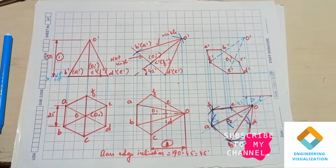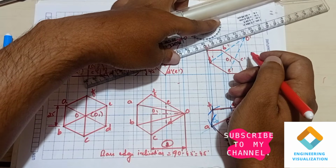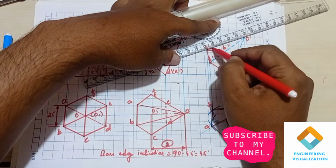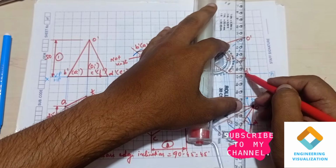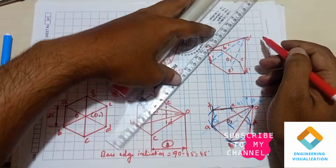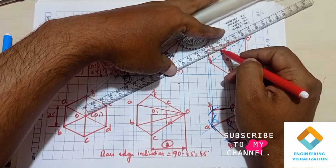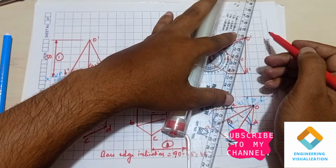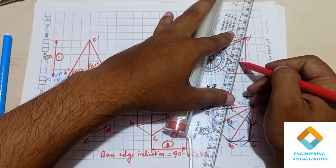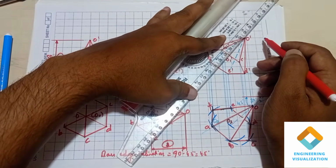Now we will be constructing the slant edges from outside, that is from A dash to O dash, D dash to O dash, B dash to O dash and C dash to O dash. These are passing from outside of the base of the hexagon. That's why they have to be written with a continuous line. Now finally we have an axis.